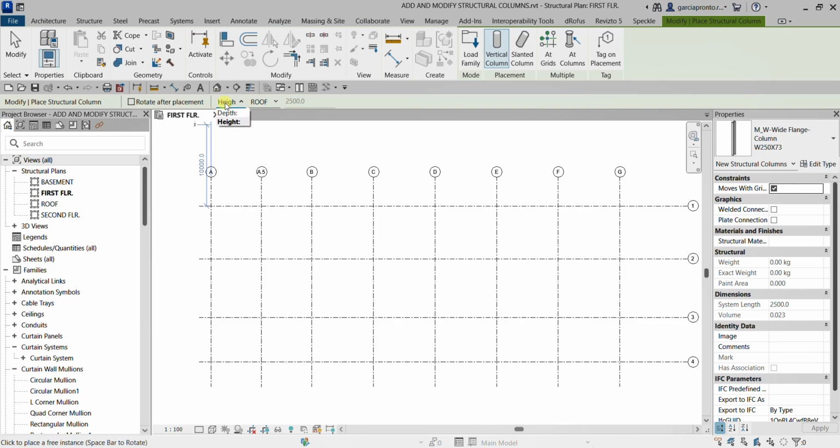So if you are going to select depth here, what will happen is from your current floor, it will go down. So that's the setup. If it is depth, current floor going down. If it is height, current floor going up. Okay, so now I'm going to make that roof. So first floor to the roof.